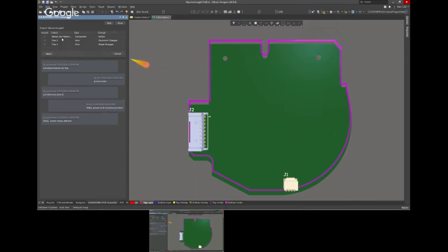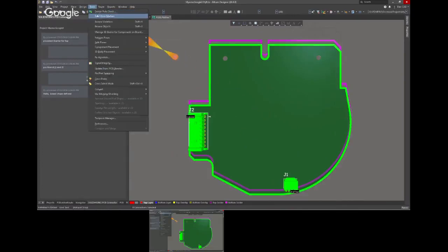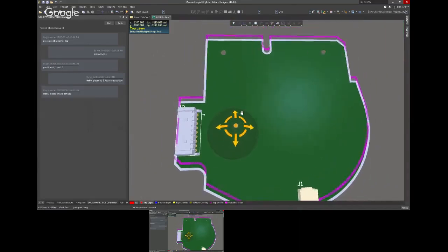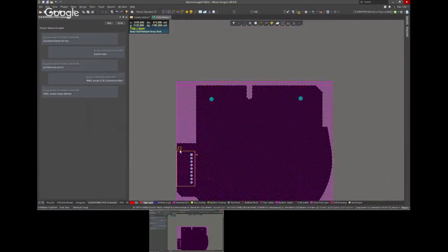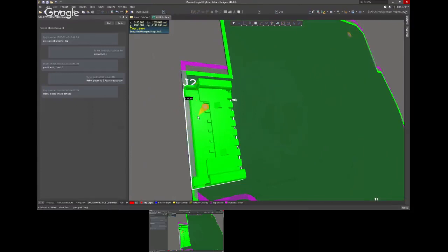I can see that I have the 3D body here. I can click and highlight the change; here are the bodies highlighted. I'm going to accept it and apply it. Now I have the placement barrier. Let me reset the error markers because it's complaining; I already have components sitting too close to the board edge. I can define my component placement rule in Ultimate Designer so that components have to sit 1 millimeter away from the new 3D body that came in. Make sense? You notice how it's now interfering, because the 3D body of that connector is colliding with the body of that new barrier.